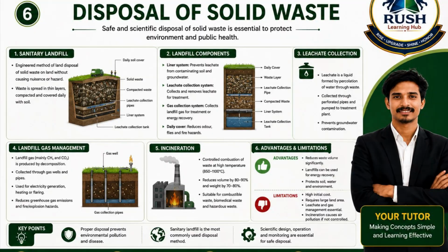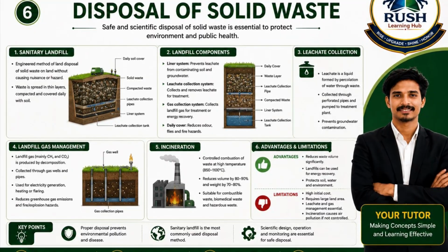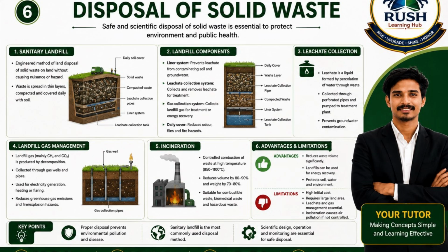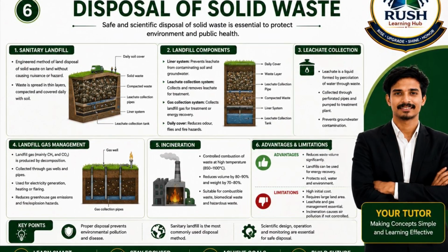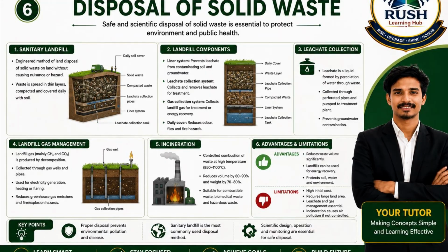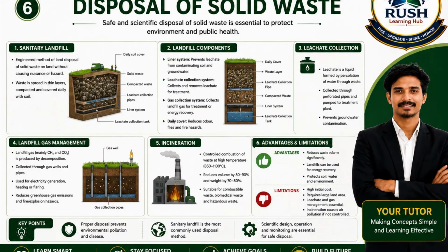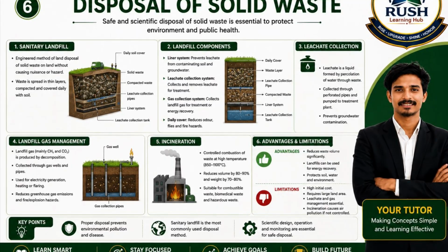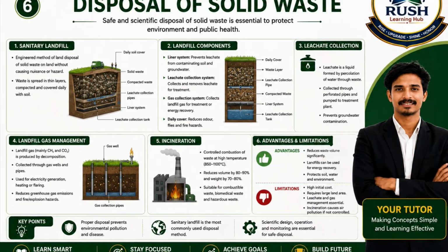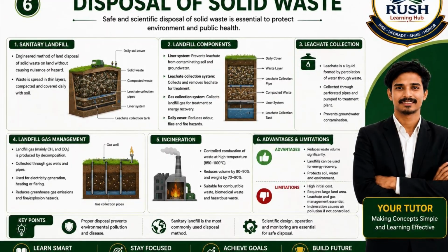Now let us discuss the daily cover. At the end of every working day, the deposited waste is covered with a thin layer of soil or other suitable material. The daily cover performs several important functions. It reduces unpleasant odors. It controls flies, insects, and rodents. It prevents waste from being scattered by wind. It also reduces the risk of fire.